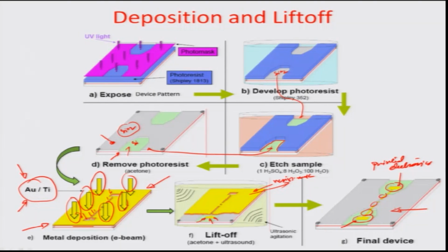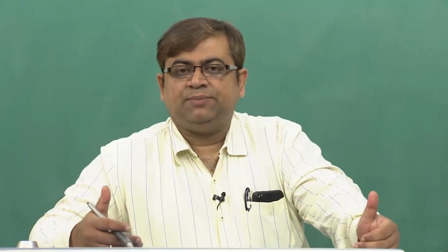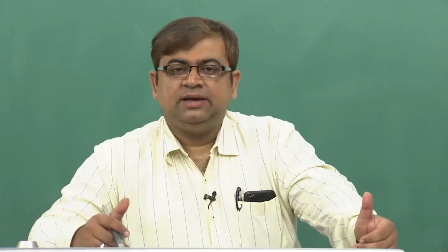So, with this photolithography and a combination of various processes, like in one case you saw the etching process, how it combined with the lithography. Another case you saw the deposition process again, which combined with the lithography, and then the liftoff process. You are able to generate various micro machined features or micro machined structures by assembling these processes together. So, these are one of the most advanced sort of first generation advanced microelectronic processes through which you could achieve structuring or featuring at the micron scale.